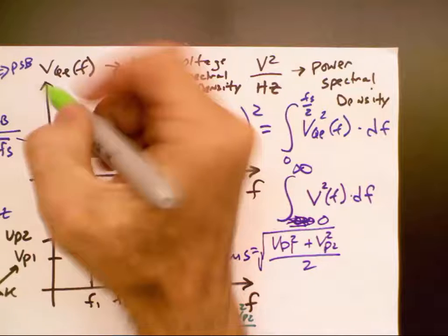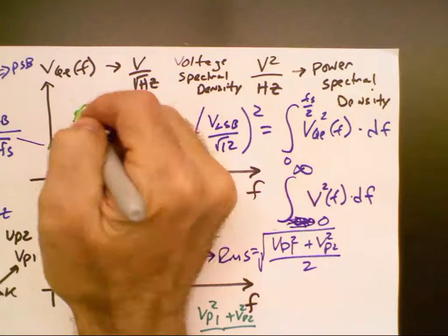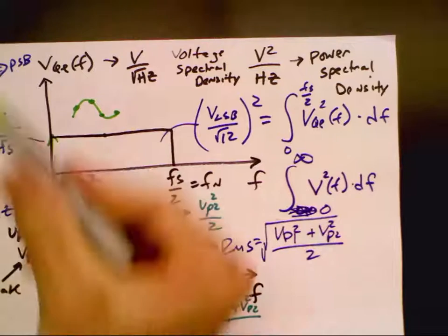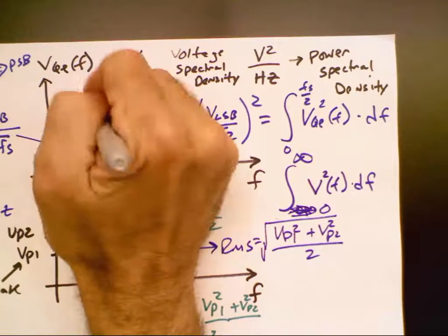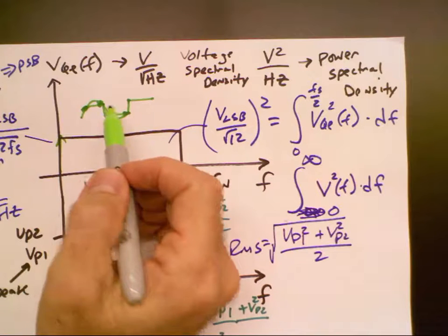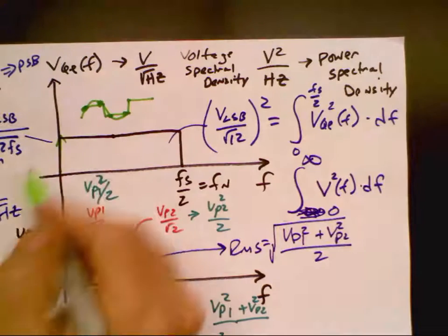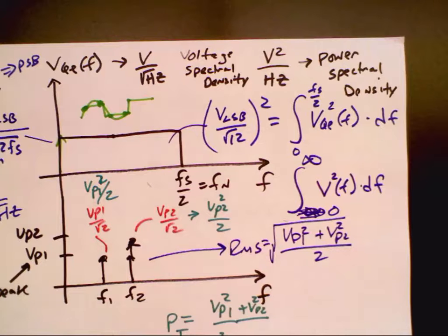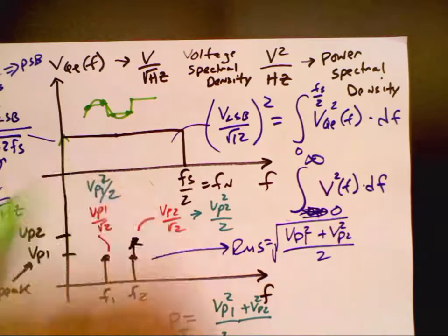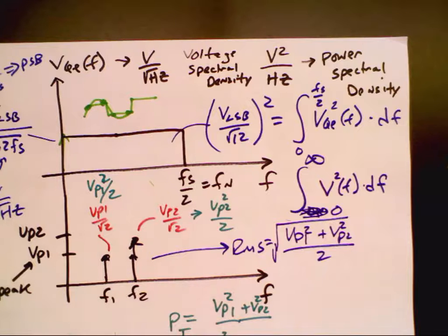If I put in a tone that's locked where I'm hitting the same points over and over again, and I look at the spectrum, I'm going to get an output which has tones. If I hit, let's say, a flat level like this, if you remember your basic signals, you'll get out first, third, fifth, seventh harmonics of the input sine wave because it's a square wave. You're not going to get a nice spectrum, you're going to get discrete tones. Any questions? So what I'm getting at, again, nothing magical. The model has limitations, it won't work all the time. Okay, so let's go look at figure 514.